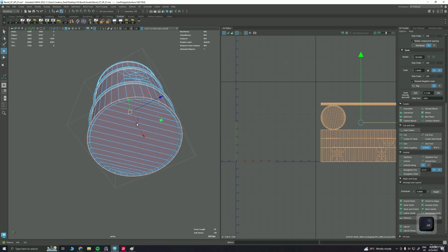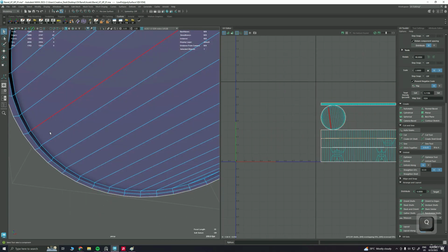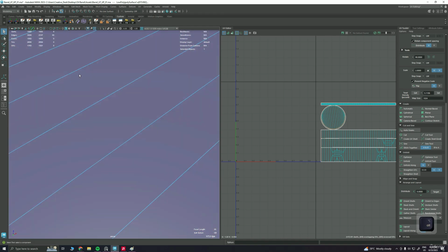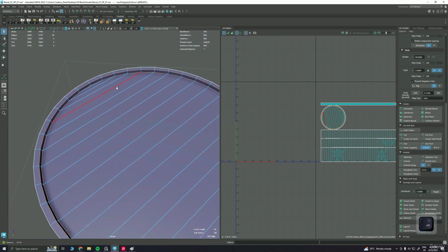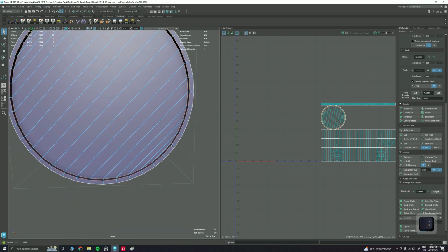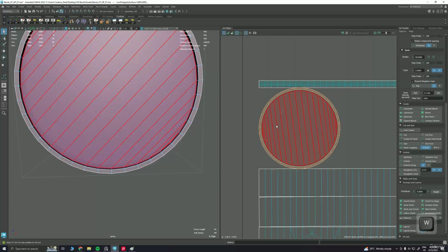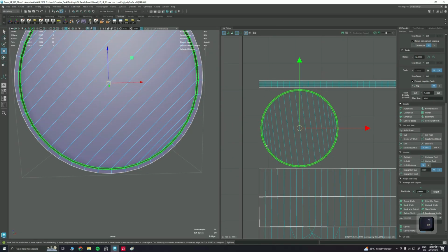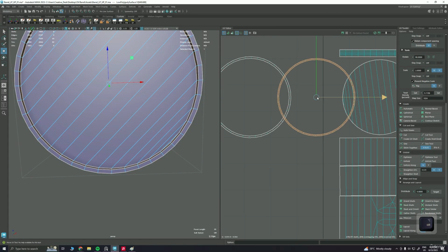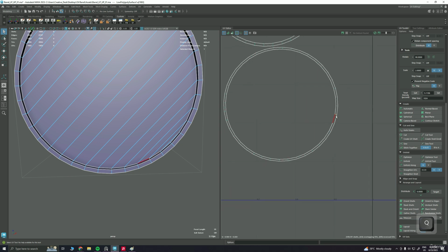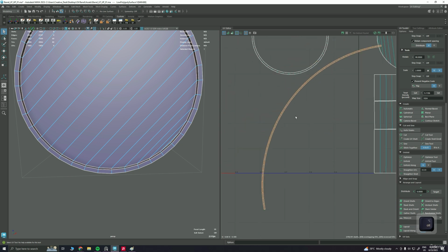Let's lay out the UVs for, okay, we forgot to cut, like I told you, cut wherever the 90-degree angles are. So we'll have to cut here also to avoid normal baking issues. So let's move this out and let's move these out, and let's make one cut over here, and let's unfold this.